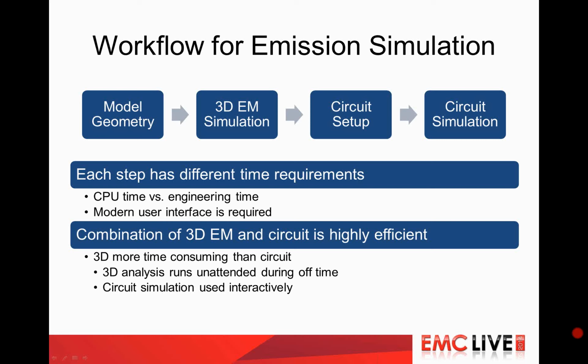So you can see that both methods are quite complementary, and that's a very general rule of thumb, I would say, and this is what we do also in the example here. We use the time domain method for the calculation of radiated emission, and the frequency domain method for the conducted emission, so the low frequency emission. But that's a very general rule that I'm giving you here, and it always might be the case that both methods can be applied to the same problem.